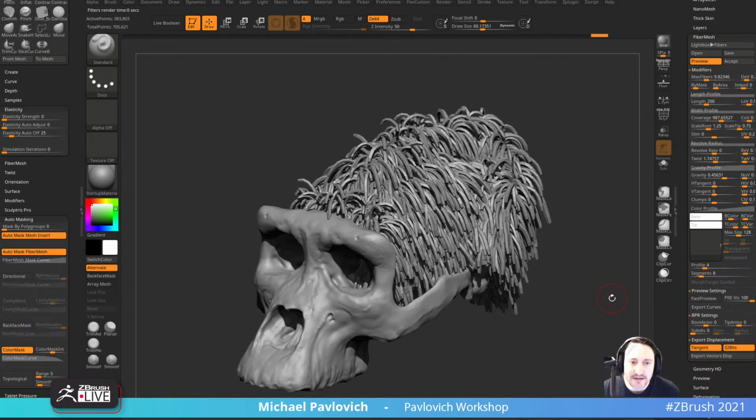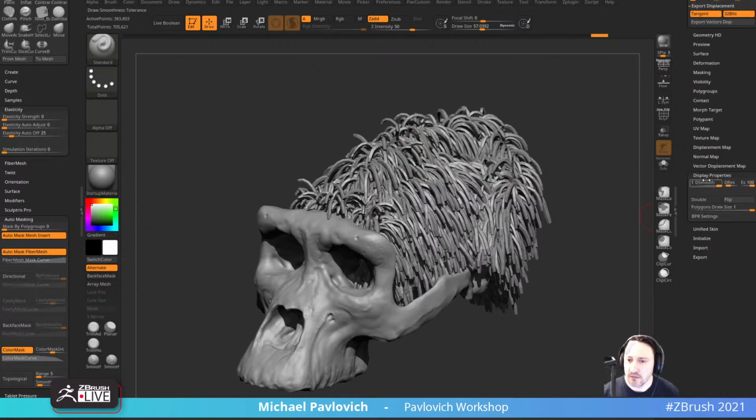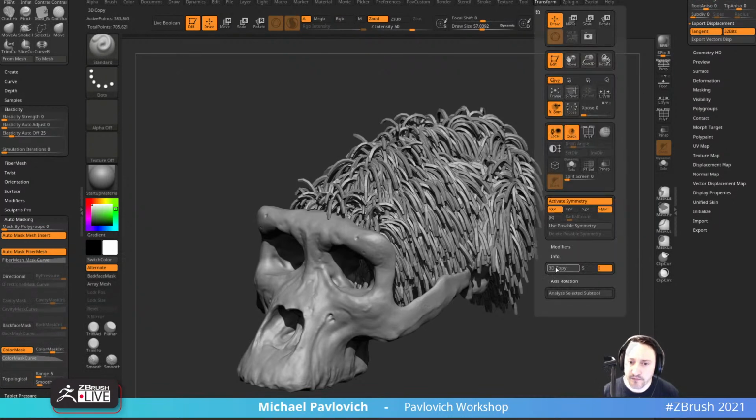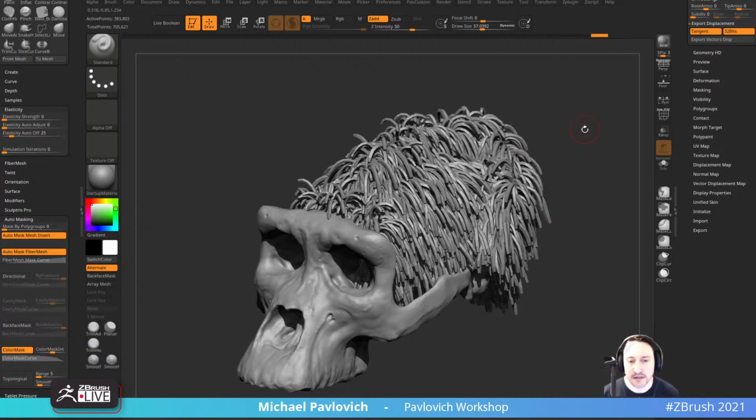As far as getting this to print correctly, you'll have to do some work with probably Dynamesh and then also mix in a little bit of the transform draw draft analysis, because you're going to have a ton of undercuts in there. So I don't know, it's not super fun to clean up.